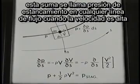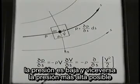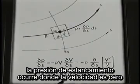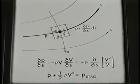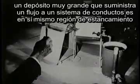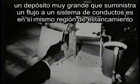On any streamline where the velocity is high, the pressure is low, and vice versa. The highest possible pressure, the stagnation pressure, occurs where the velocity is zero. A very large reservoir supplying a flow to a duct system is itself a stagnation region.